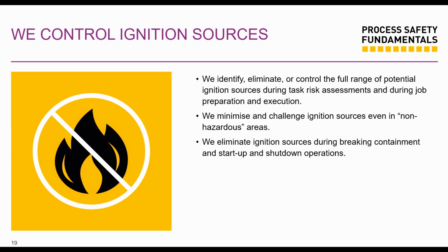Or another example is you want to do some hot work near a tank that could vent flammable vapors. Maybe it's not constantly venting. It vents every 30 minutes, every hour. But guess what? Stuff is happening that you're not aware of in that tank. Maybe some other people are doing some work downstream that could actually affect that tank, and makes the tank vent a lot more.